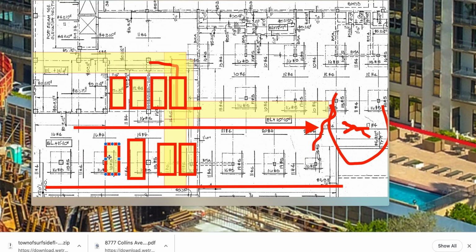Then we got one car that kind of fell over a bit, leaned over this side, rocked over. Well, look what it's rocking on top of. It's a damn shear plane. Shear plane being a column. Remember, we got the car leaning over? That's that crack. This is the fracture we see here. So we have our dividing fracture.